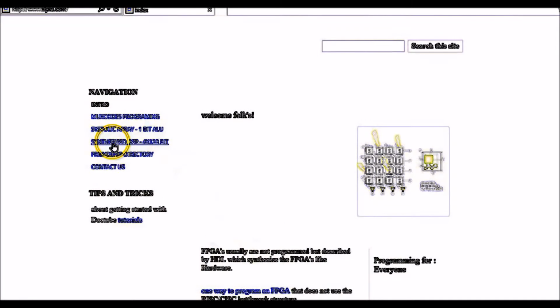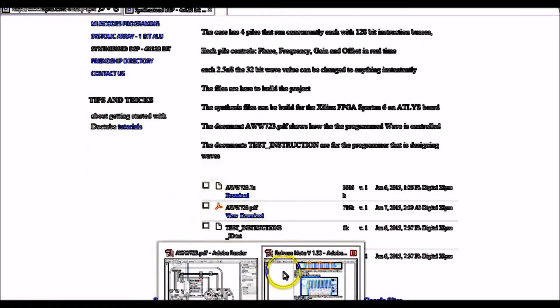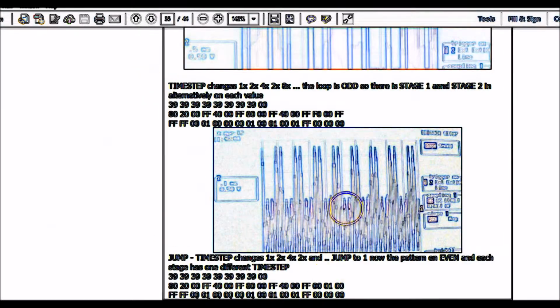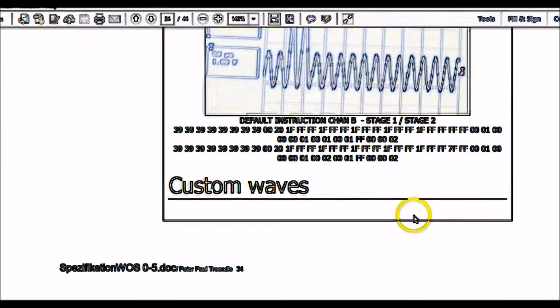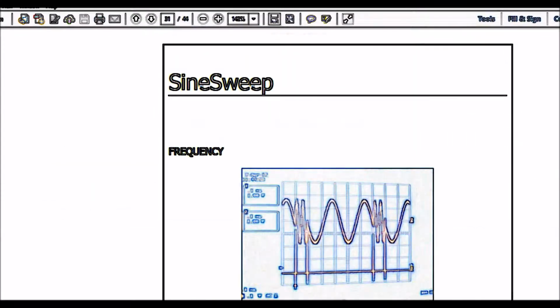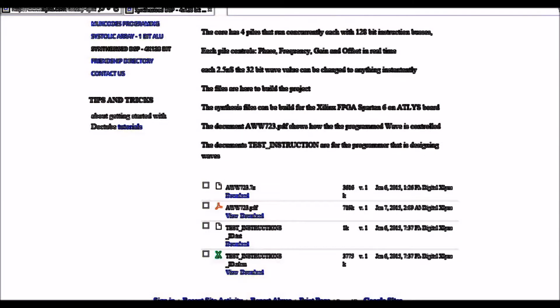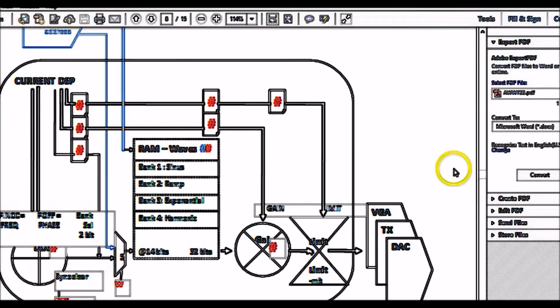My first document shows an example where many different parameters are programmed in parallel for wave generation. This requires very fast processing. The example has a very long instruction, CISC, but in implementing this DSP example in the FPGA, we have the same problems that the MIPS guys had with the RISC in the 80s. The instructions need a pipeline.